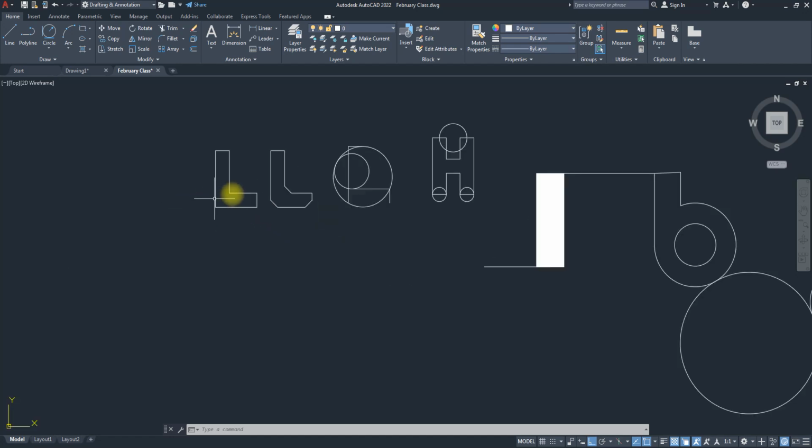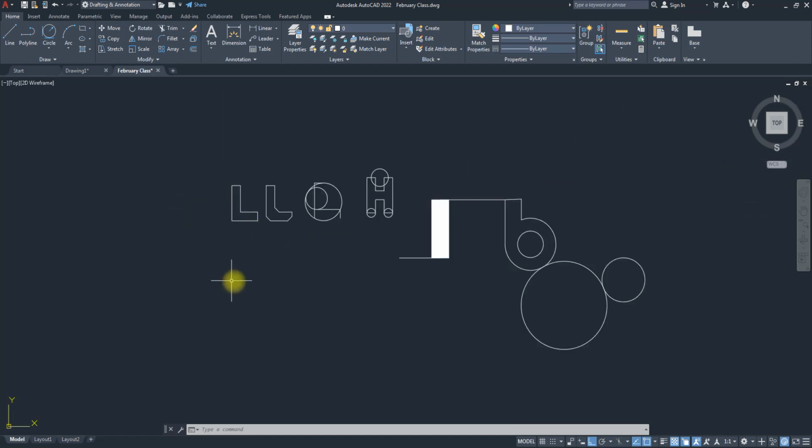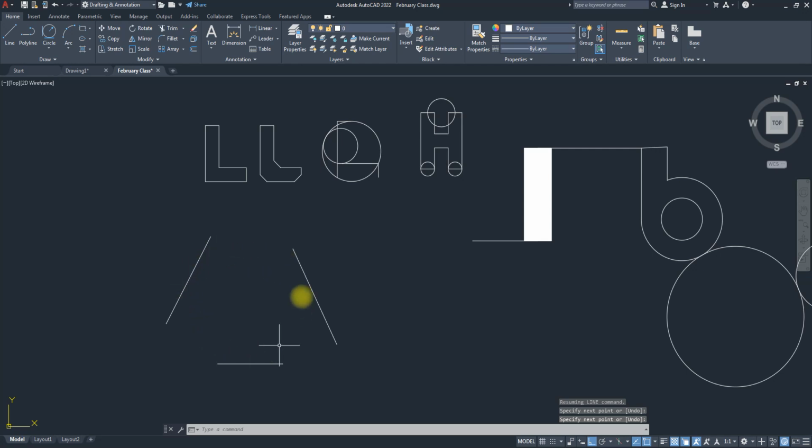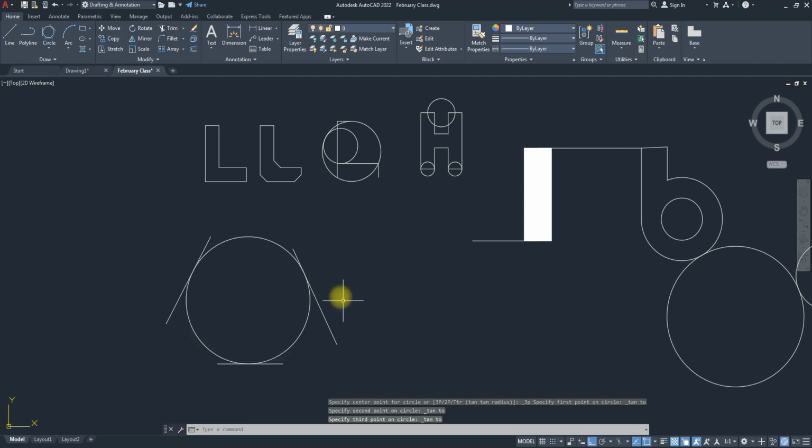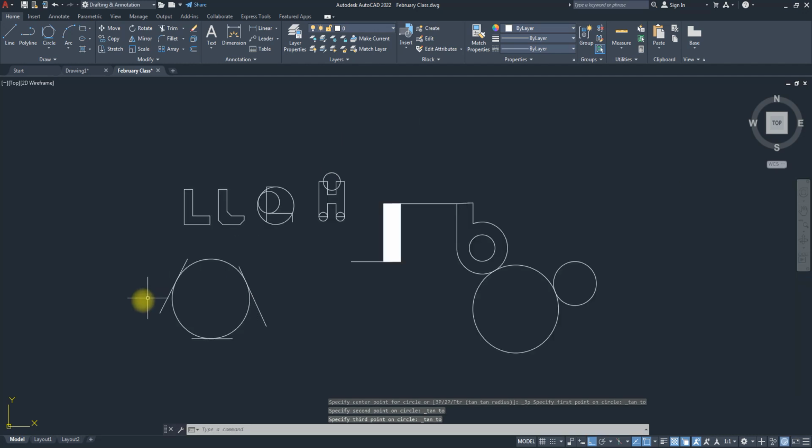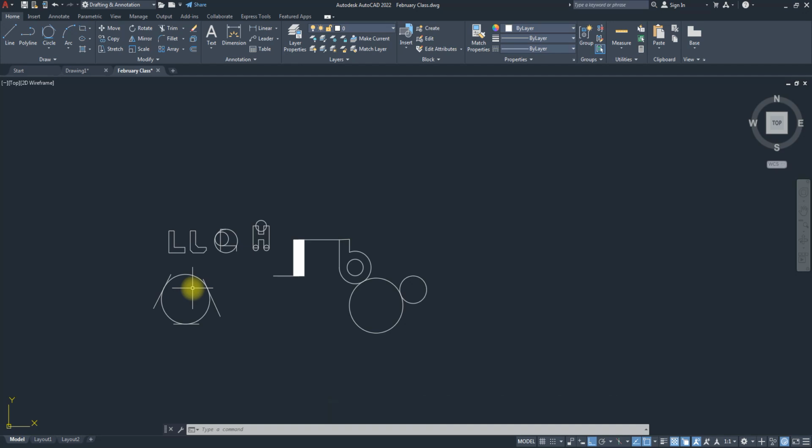Let's assume we want to, let's create a line 1 here. So turn off this. We want to create a circle such that these 3 lines are tangential to it. So we can just say tangent, tangent, tangent. Choose this, we choose the 3 lines in any order that you want. It's going to create them. So that's what the tangent, tangent, tangent does.